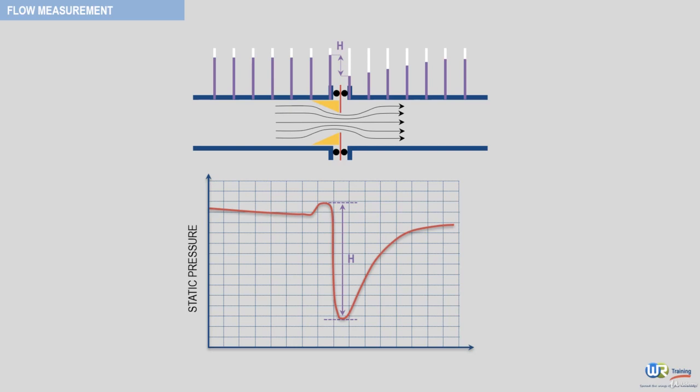Then the static pressure increases as far as the velocity decreases, and the final static pressure is not as high as the initial one because of frictions due to the orifice. Now note here that a local vacuum could be generated around the orifice in the dead zones, especially in case of a low initial pressure and a high flow rate. In case of even a small tightness failure, air enters into the pipe, which represents a safety issue.